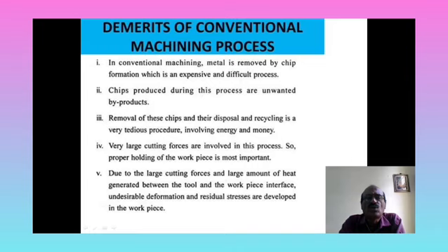The fourth one, very large cutting forces are involved in this process, so proper holding of the workpiece is most important. Due to the large cutting forces, a large amount of heat is generated at the tool and workpiece interface, and undesirable deformation and residual stresses are developed in the workpiece.